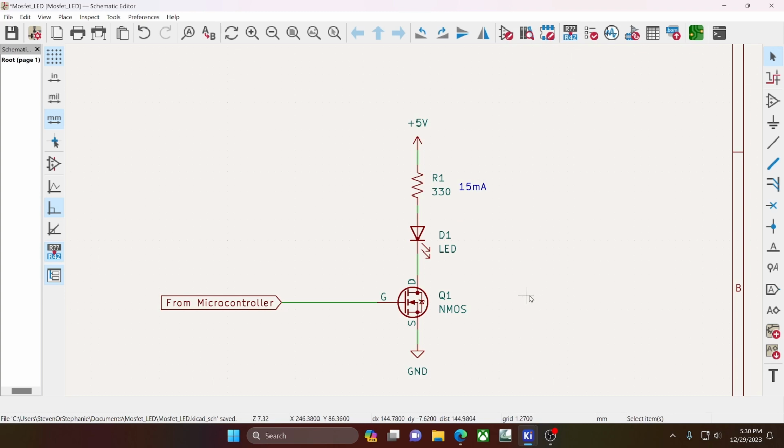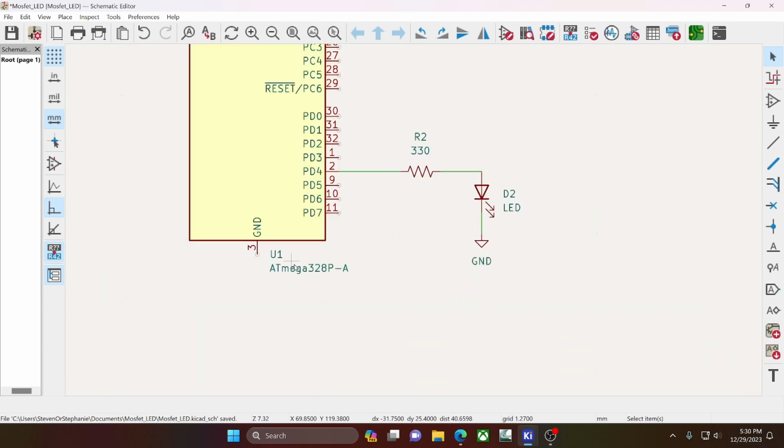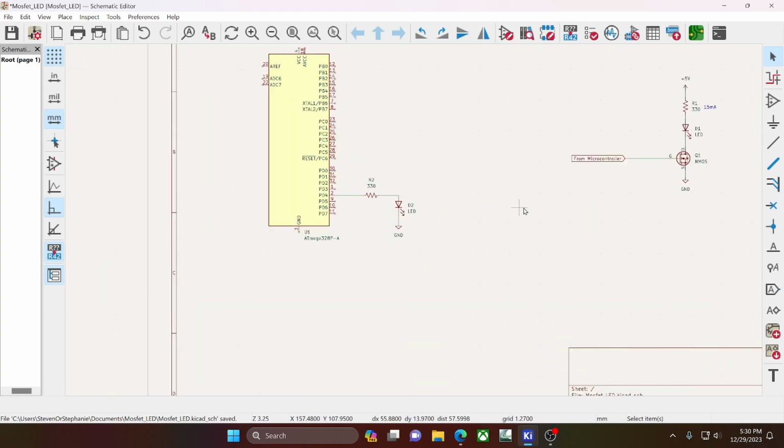For starters, this LED can do more. You're only limited by whatever your 5-volt supply can do. And that number's a lot easier to look up. And yeah, switching the resistor, no big deal. Switching the LED, no big deal. Supply chain stuff happens. There are other vendors for all of these. There are not a lot of vendors for an ATmega328P.